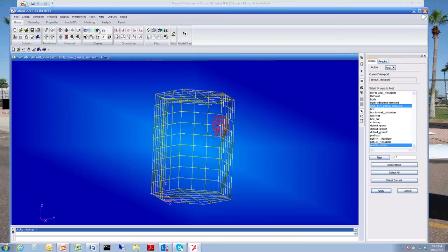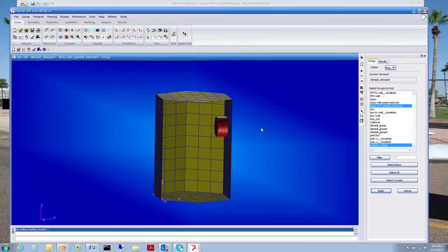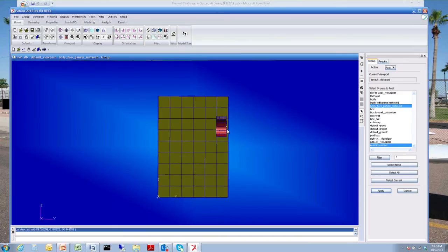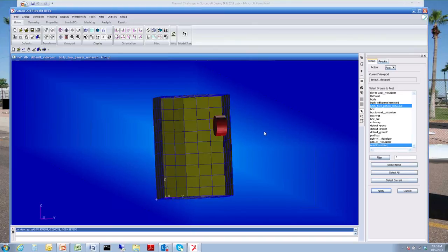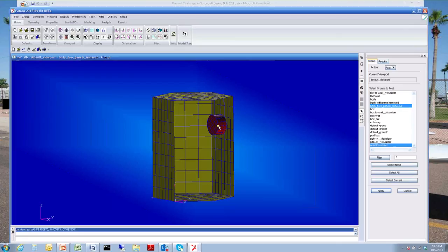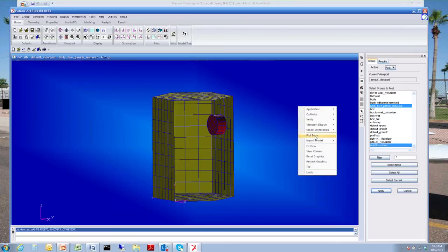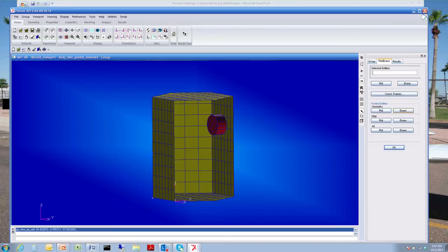You can see the reaction wheel is on this side here, and there's a little bit of a gap between the reaction wheel and the radiator panel it's tied to, and that's okay because our contacts, we call projection contacts. They'll actually take the cylinder, the bottom part, and if I turn off my elements here for a minute, let's erase elements, it'll take that bottom part of the reaction wheel and connect it to that panel.